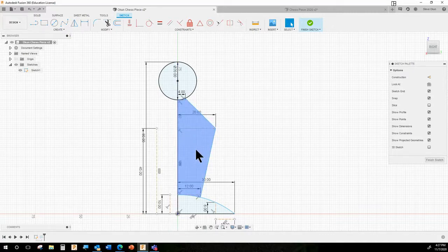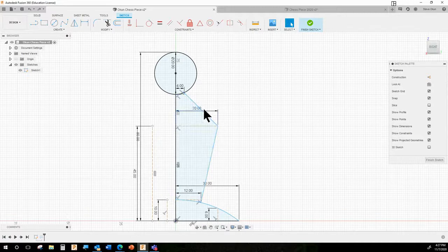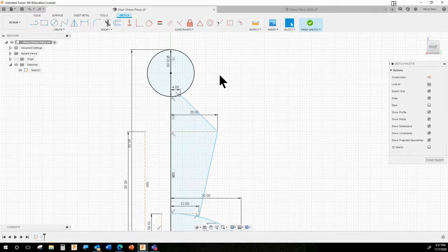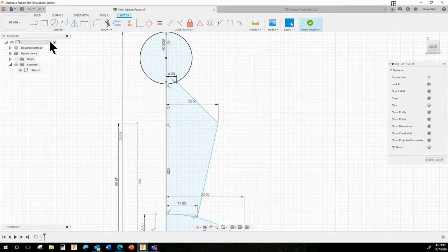And in the Lego piece, we used offset, but we can't use offset on an angled piece like this. We're actually going to have to draw those lines, and it'll help me teach you how to make parallel constraints too, which is sort of the whole point. So I'm going to use the line tool.